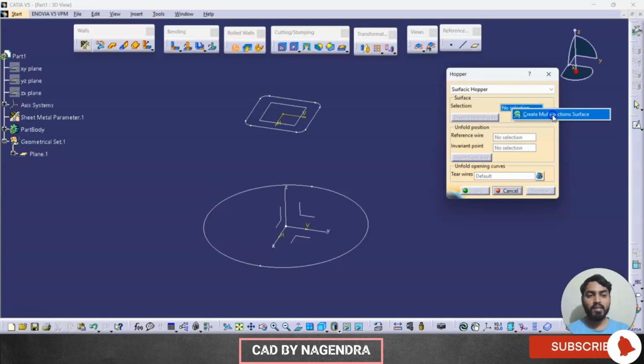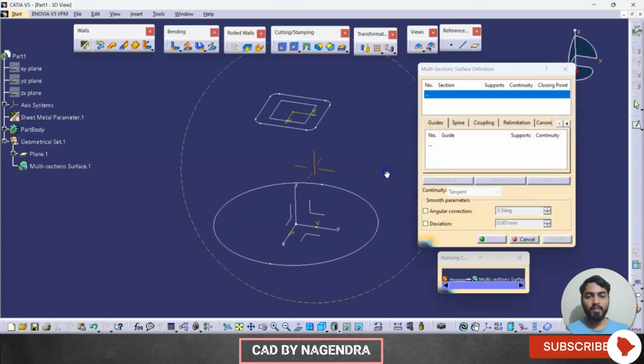We used create multi-section solid in part design. Similar to that, here we are going to create a multi-section surface. Why? Because directly in sheet metal we can't add material between these two profiles. By using this we convert the sketch into a surface profile which will have no thickness. Later we are going to add sheet metal thickness. So I will click on create multi-section surface.